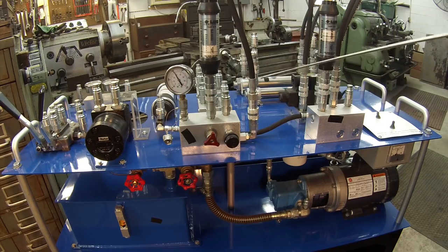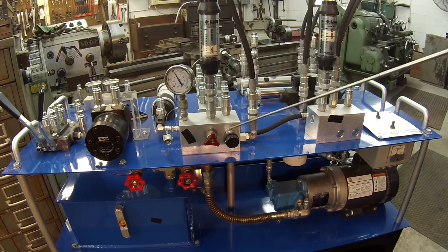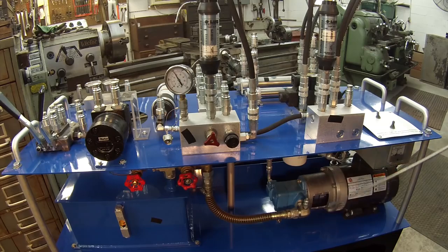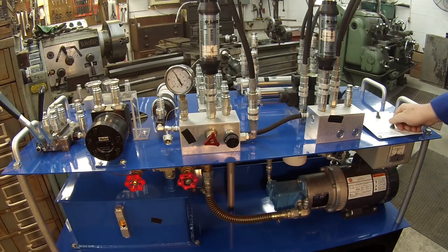I'm not doing any work, but the pump is still pumping fluid. Alright, where is that fluid going? Okay? It's going over this relief valve right here and going back into the tank, through this filter back here. Alright, so the only way you see fluid right here is when I actually actuate this cylinder and make the cylinder go in and out.